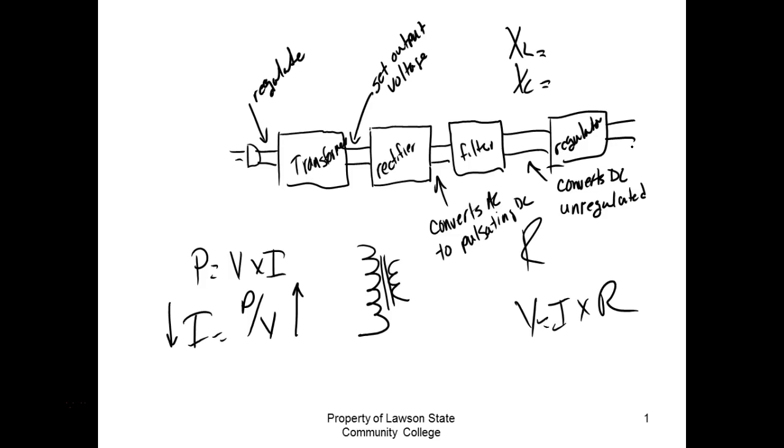We got another power supply out there called a switch mode power supply, which we'll also look at. But these guys are easier to troubleshoot. They're easy to design. So y'all already know some things, right? We know we got to get a transformer that's going to be able to establish our output. We know we got to get a transformer that's rated at the current that I want on my output, right? When you buy your diodes, you got to make sure that they got a breakover voltage that exceeds your input voltage, probably by double. And then you got to make sure your rectifiers can handle the current of the output, right? That makes sense.